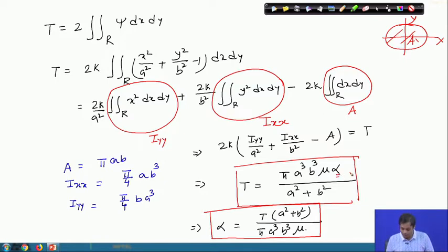Great. Now, whether it is a circular cross section or a non-circular cross section, one assumption we kept the same, and that assumption is that the angle of twist is linearly proportional to the longitudinal coordinate axis. Now, once we have the angle of twist, let us find out what stresses we have.